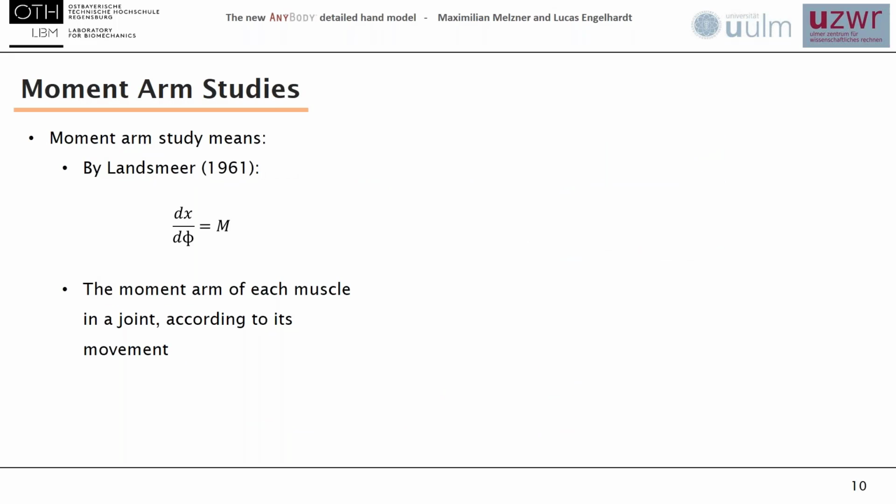The tendon excursion method introduced by Melzner et al. was used for the first step. This method uses the length variation of the tendon, where only one axis of a joint is moved, and the articular-angular change of the joint, to calculate the moment arm of the specific muscle with respect to that chosen joint.